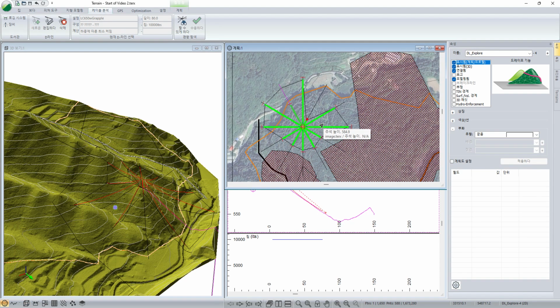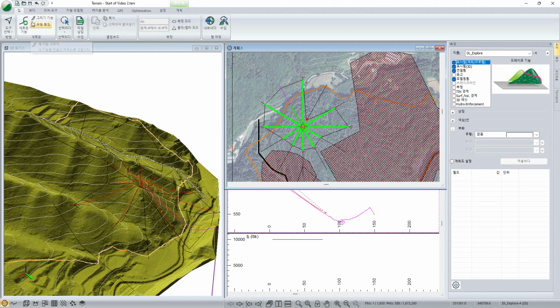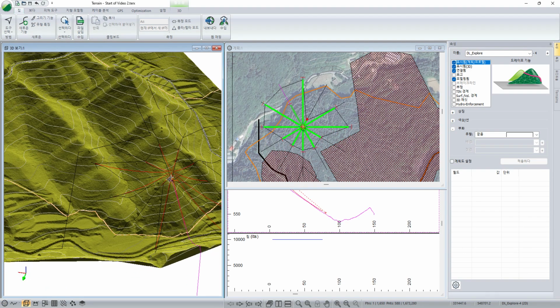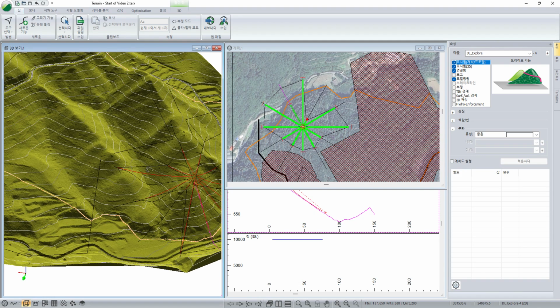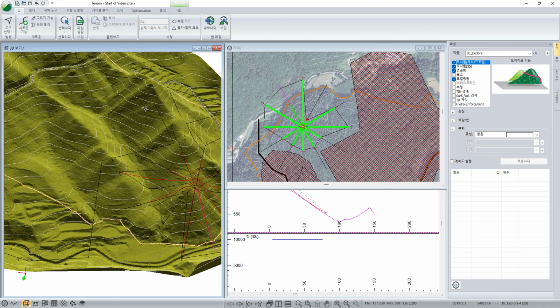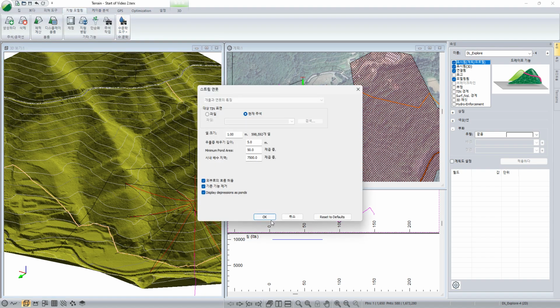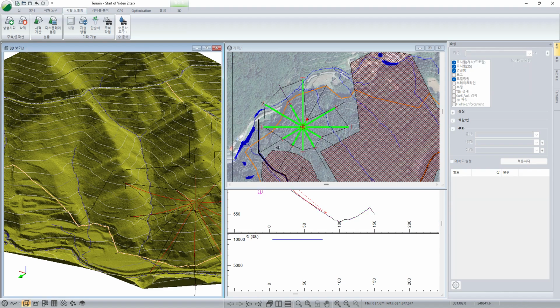So here we're going to use another tool in the toolbox, and that's Path Explorer. So we're going to plan our road to get a landing into that location. With this, Path Explorer considers earthworks costs, but we'll also probably want to consider our crossing costs in this. So we'll use our streams and ponds to generate the flow vectors.